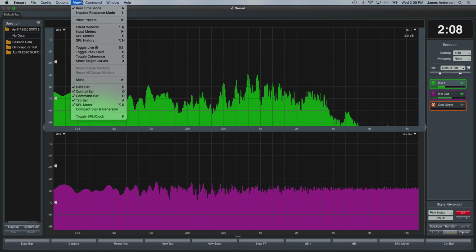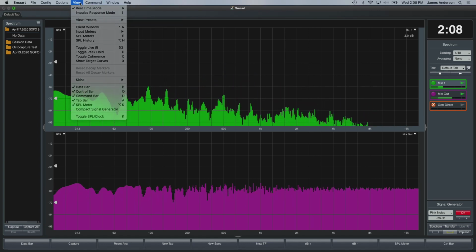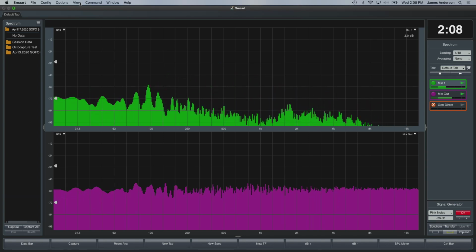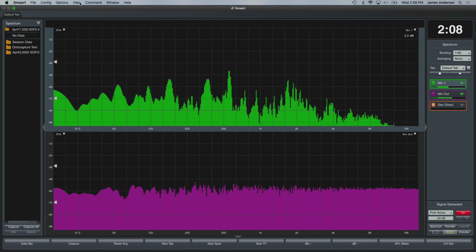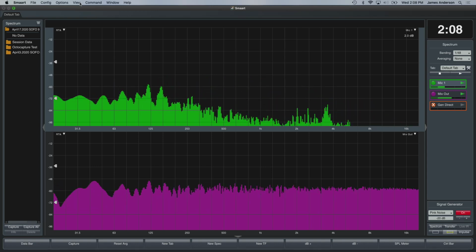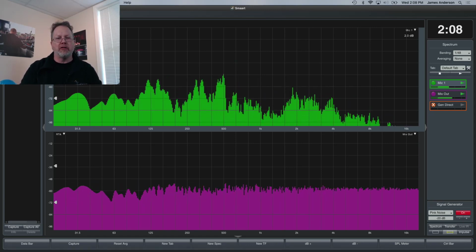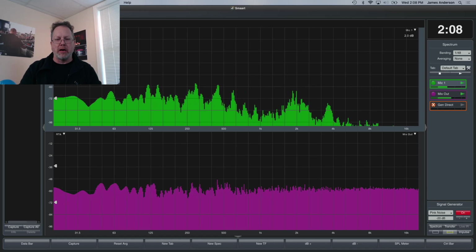You'll notice that the hotkeys for doing it are R and I. If you notice that you're storing a trace and typing in a name and things are going wild, oftentimes you think you're typing into the data field, but you've already hit enter on the data field and now you're just typing random hotkeys.